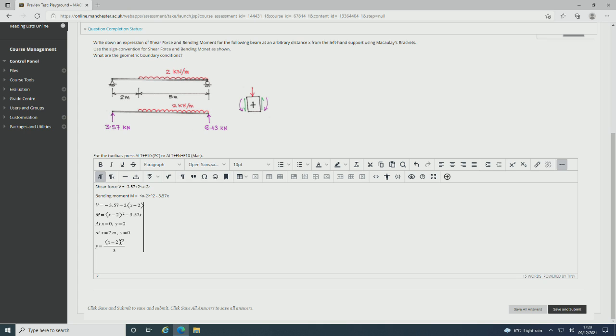So the more material away from the axis, the higher the second moment of area. Yeah, that is because of area times d squared. More material away from the axis has got a higher second moment of area.